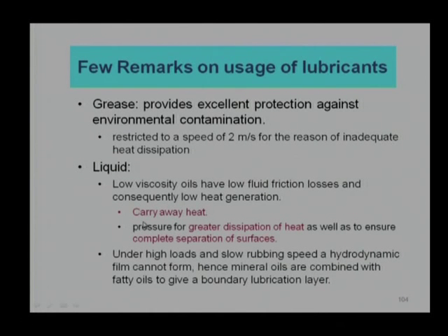Now, these low viscosity oils are also preferred from the cooling point of view. That is why I say they can carry the heat. In addition, they are preferred from the feed pressure point of view. If we are trying to levitate one surface over another surface, or keeping a separation between the surfaces, sometimes we force feed the lubricant and pressurize it between the two surfaces. In those situations, again the low viscosity lubricant will be preferred, because a high viscosity will give more resistance to pumping, and more resistance to pumping means more power consumption. So, power loss will increase, and the cost will increase.